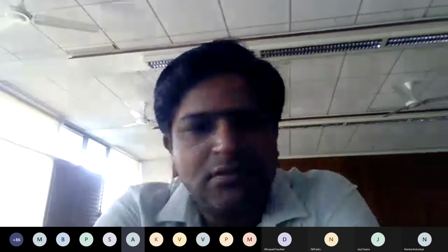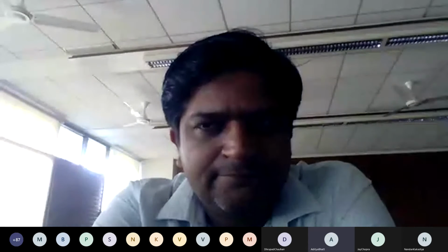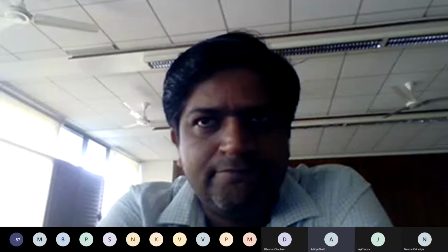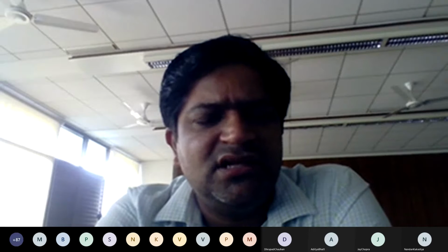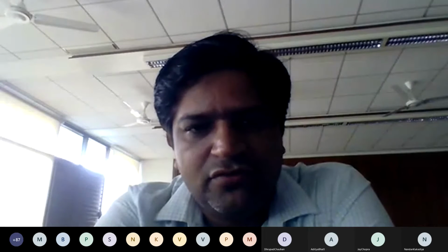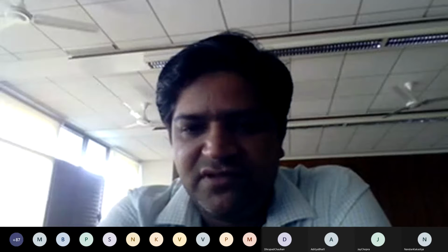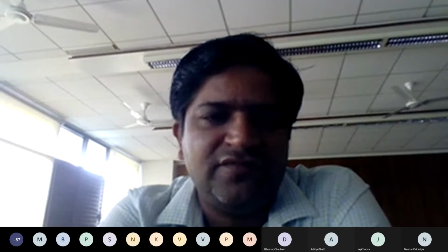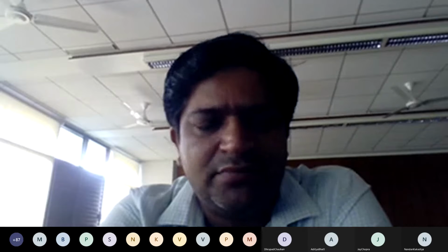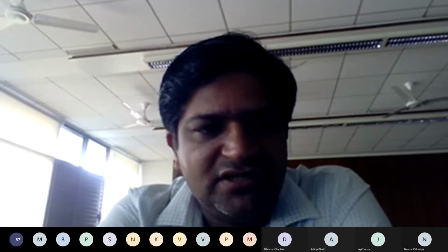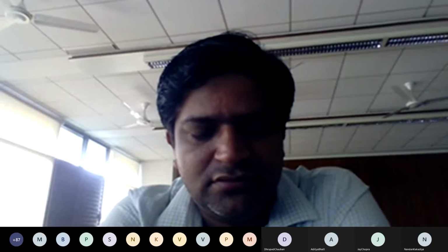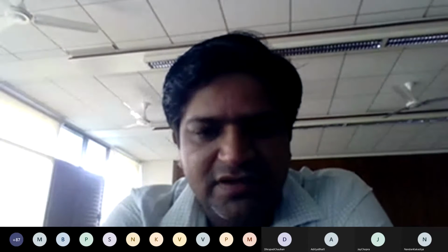Sir, the starting and ending points of the two phases are not the same in non-continuous, means they are different. Yes. So there is phase discontinuity which is happening in a general FSK, right? And it is not good. So we obtained a continuous phase frequency shift keying in which the transition from one phase to another phase is smooth rather than an abrupt change in phase. And how do we ensure that? Can you answer? How do we achieve CPFSK?